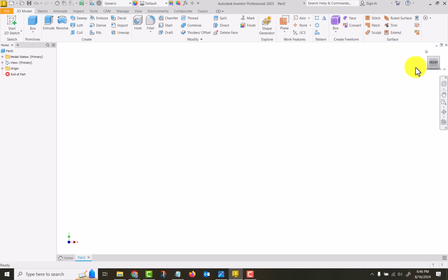When you're in Inventor, just like AutoCAD, it has the view cube over here. We've also got our UCS down here, which is different from AutoCAD. This is not the 0, 0 point. This just shows you the axes, okay? And you can drag the view cube to rotate it, and you saw how the UCS turned there. You hit the home key, it takes you to an isometric view, which is the way most parts will save.